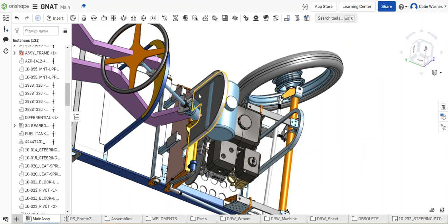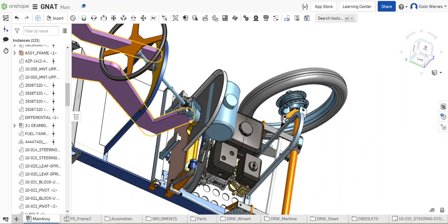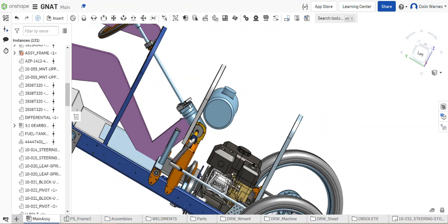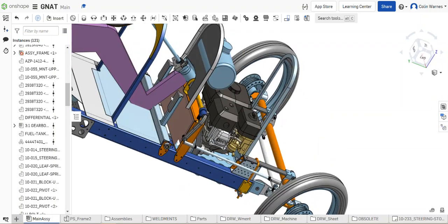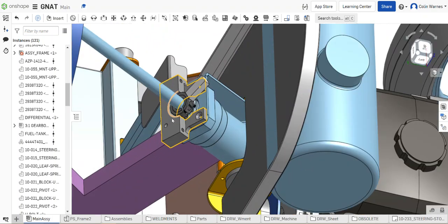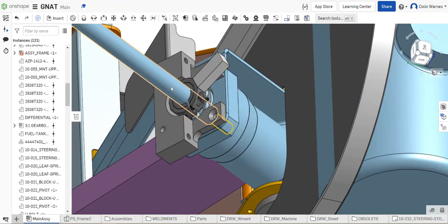But the problem is that with the 3-to-1 gearbox and this large steering wheel, you actually have a lot of torque, and I was finding that I could over-torque the gearbox, and certain things were slipping as a result of the excessive torque when hitting the stop. So what I created, and I'll hopefully be installing these parts soon, were some physical stops on the actual steering shaft.